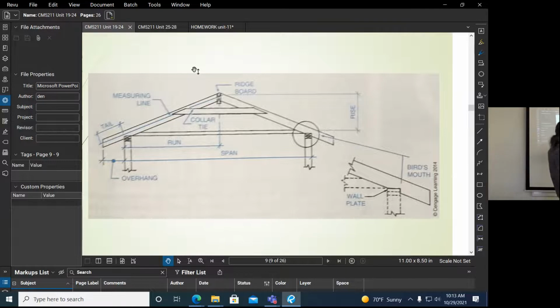And then instead of having truss members in here, we tie the rafters together with what they call the collar tie. This keeps it from spreading out. If you don't do the collar tie, those rafters have a tendency to flex outward. And then this is like a ceiling joist member that runs across, and then you attach the drywall underneath there to finish off the ceiling.